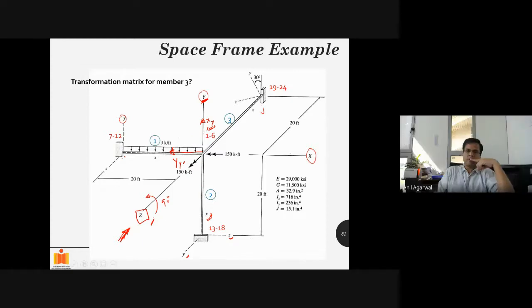So I will rotate about x, again looking into x in the anti-clockwise direction. When I do that, in that process, my z will come here. I'll call it z alpha. This is alpha rotation, right? This is alpha transformation. And this y will come here. I'll call it y alpha. So z will be aligned with z alpha, y will be aligned with y alpha, and x will be aligned with my x gamma, or that is now x alpha after alpha rotation.